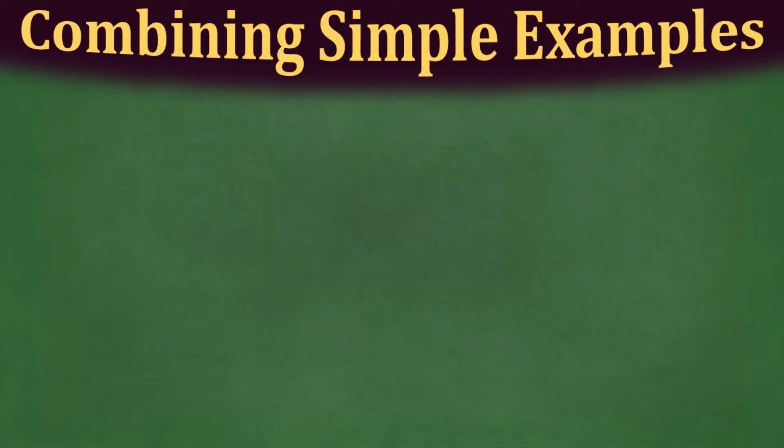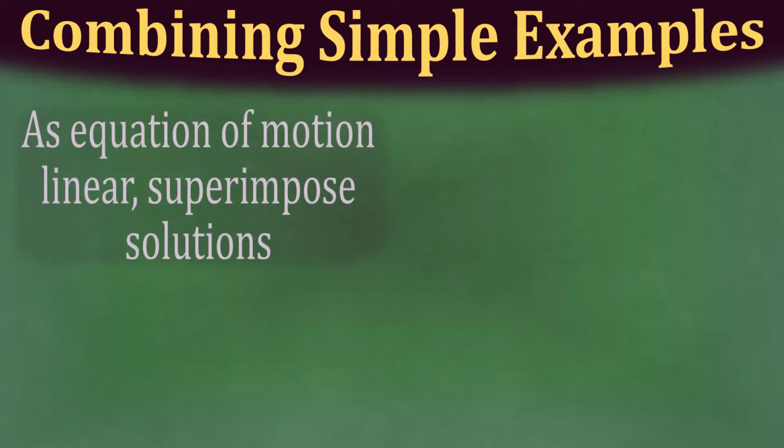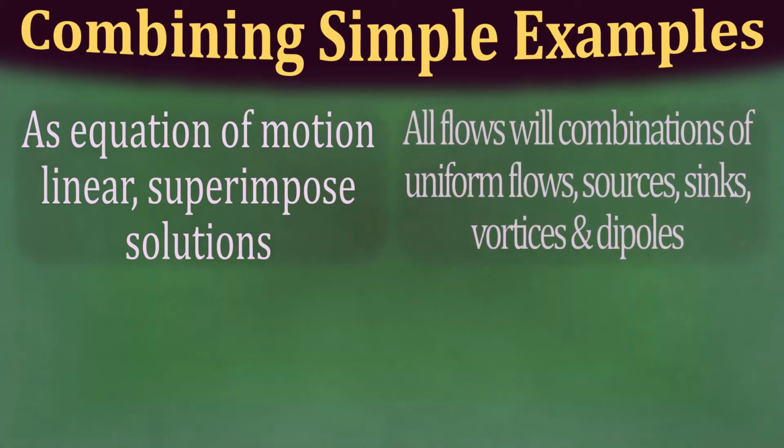Next, let's discuss combining simple examples. As the equation of motion, i.e. Laplace's equation, is linear, we can superimpose solutions. Note, all the flows we will consider are combinations of uniform flows, sources, sinks, vortices, and dipoles.